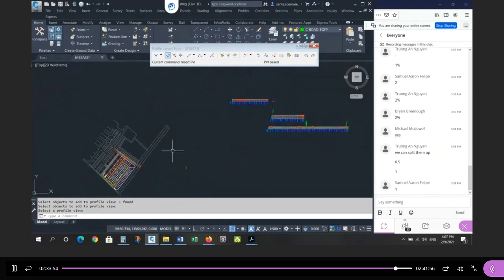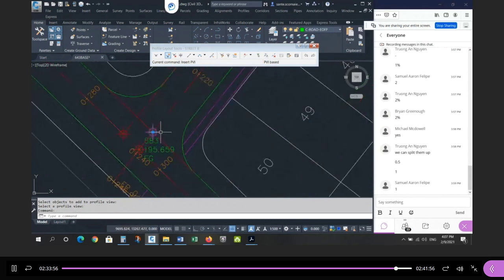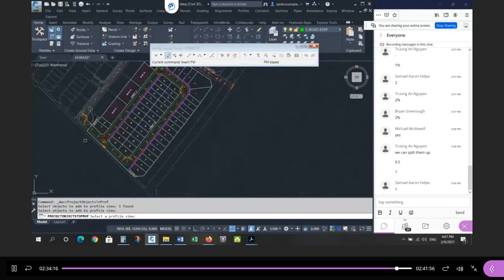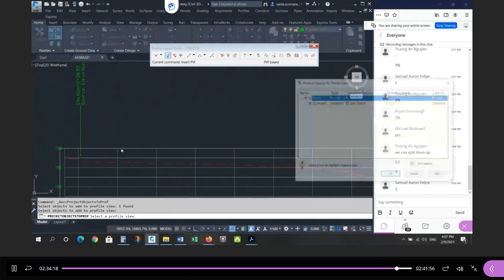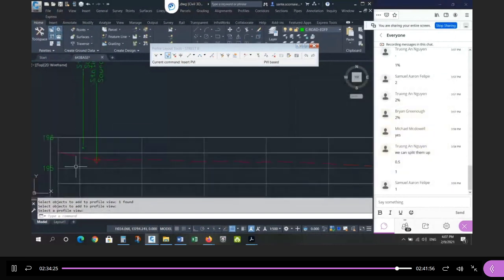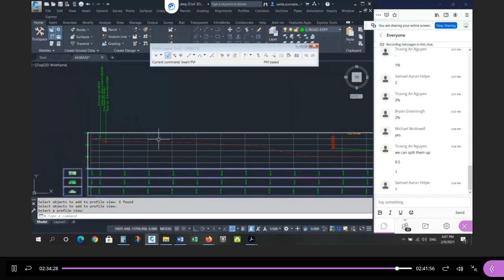Okay? And now we want to know where the edge of pavement is. So I want to know what the point is again, right? This is the projected gutter, right? Offset the center line 4.3. That's how I found this point. I'm going to project that point to the plan, to the profile for reference. It doesn't have an elevation, so I need to bring it to the elevation of the existing ground. Again, it's the station I'm interested in. And there's the station.